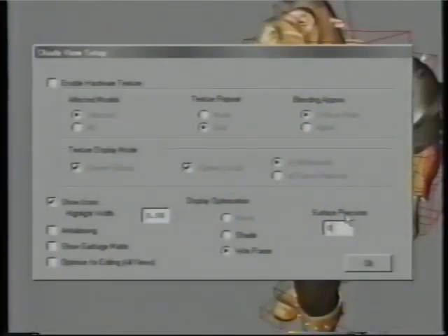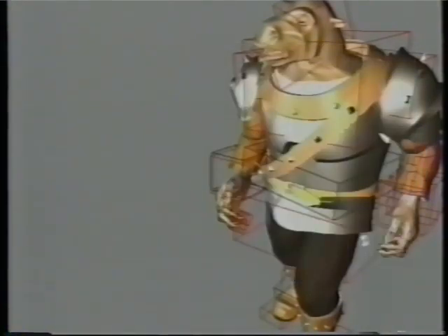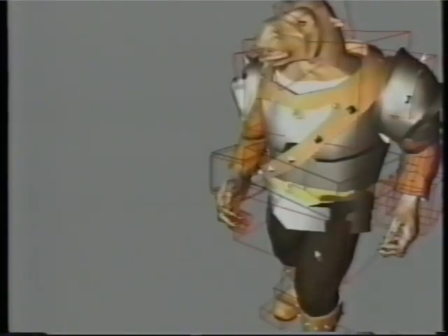Now with shaded mode on, you can see the resolution of all these NURBS objects, but the scene updates rather slow. In the shaded view setup, I can go into surface precision here, change the default of 0, meaning make the amount of polygons be whatever each individual object has set, and change that to something low, even as low as 1 for animating purposes. It displays much faster. After the first redraw, then it redraws very fast.